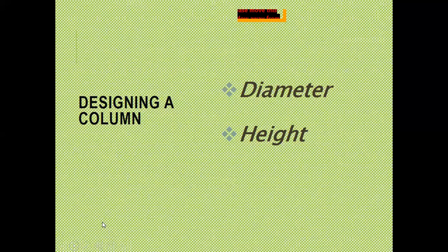Now, we're already done with using material balance equations. That way, we can determine the solvent requirement, the optimum solvent requirement, the trace in our column, or the stages in our column. Now we're ready to go into designing the column itself. So the first part is all about the application of material balance equations and equilibrium equations. Now we are into determining how large a column we need and how high a column we need for a particular separation.